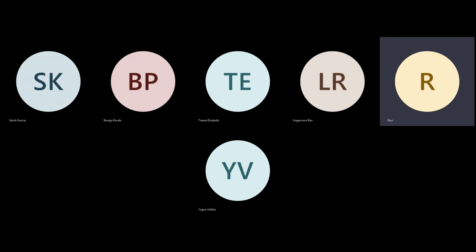So you'll have to completely create a ring around that and isolate it, so that for the VDD continuity issue you can connect it, but it has to be separate. Even though it's a single voltage, you'll have to create domains and a separate block. That will be a separate partition, but manufacturing and yield losses can happen. So this should be your answer: first of all, it's not allowed, not recommended.